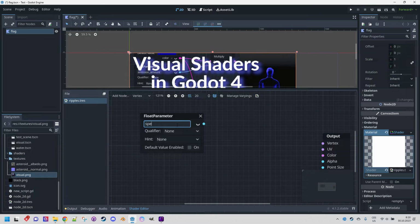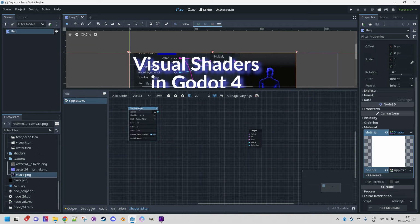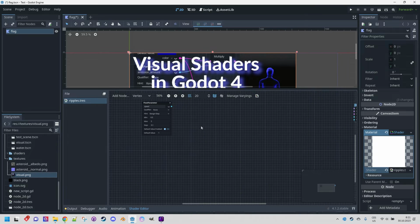Let's call it speed, and the hint would be, let's say, range plus step, so from 0.5 to, for example, 5, and the step 0.1. Okay, let's define the initial value, that would be 2. Very well, I think we'll need a lot of space here, so I'll just move these nodes over there.